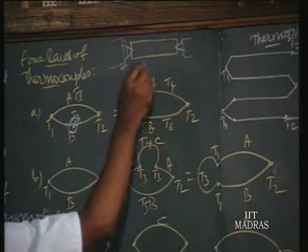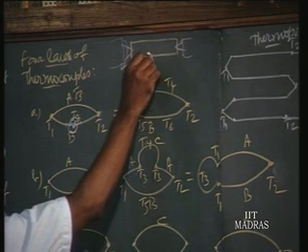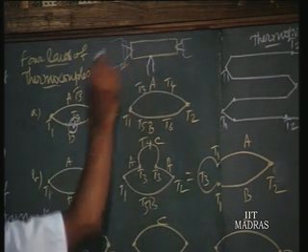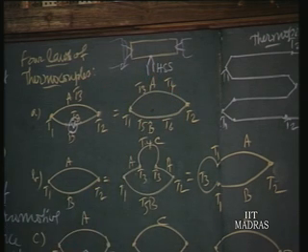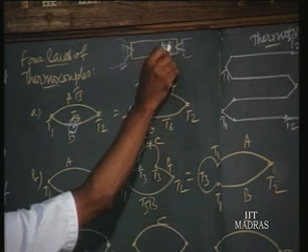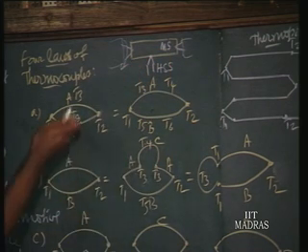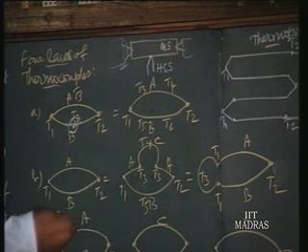And when we have the cutting tool somewhat like this, this is the hot junction. This temperature is to be measured, and normally the cutting tool is made of high-speed steel. The material may be mild steel. So two different materials. So it is analogous to two different elements, and the cutting point is the junction.